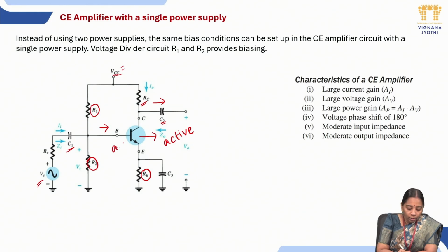So the AC signal arrives and the transistor amplifies only the AC signal. Again, at the output side we have DC, and the amplified AC signal gets mixed with it, so you might have AC along with DC at the output. Because of that, we again use a coupling capacitor here, such that the DC signal is eliminated and at the output we get only the amplified AC output. So this is all about the remaining part.